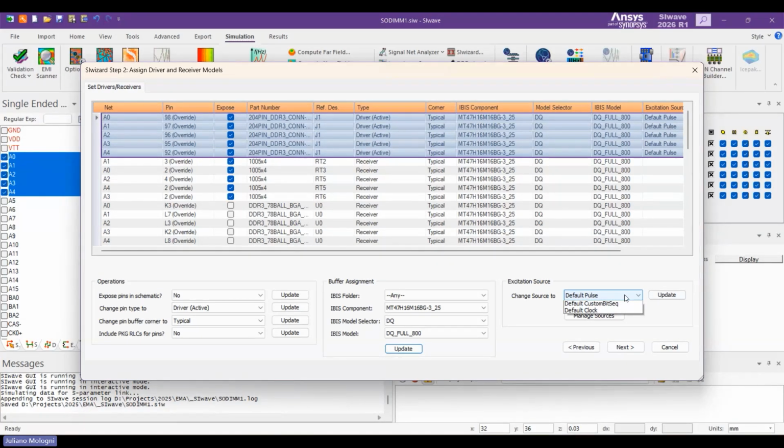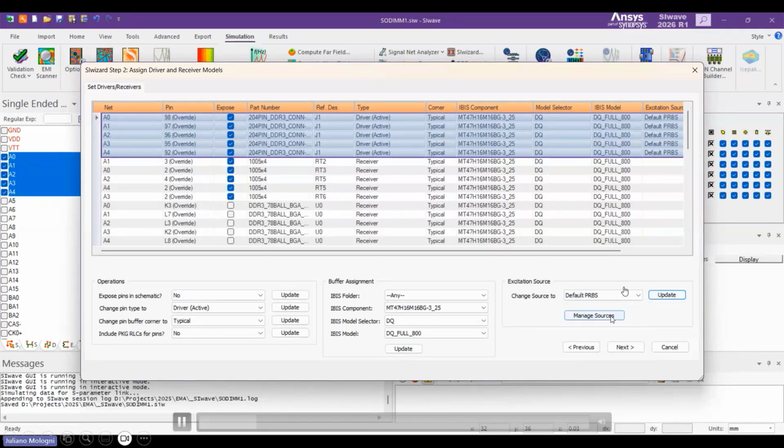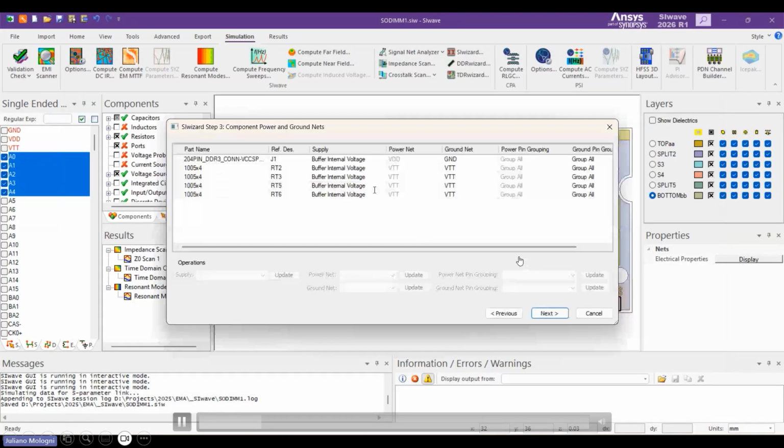That's not so much for printed circuit board signal integrity. We have IBIS AMI models, but for EMC, sometimes that might be tricky. So you might have to rely on ideal sources or measurements, right? In this case, we have all of these nets, and we have all of the components that are connected. This net is connecting all of these components. And you can set those IBIS models and the waveform. Here's a clock, but I'm going to use a PRBS, so it's a random sequence of bits.